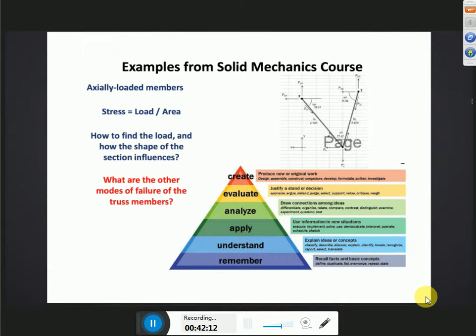Now we can tell them, even in this example, it's tension and compression in members. Compression members basically get to yielding, buckling. Now we may or may not cover buckling in solid mechanics, but if we tell them right away and then show a demonstration using a long scale or a long bar in the classroom, they will appreciate that. So before it gets compressed, it may buckle, and then leave it at that point for the equations to be discussed maybe later if you cannot cover it.